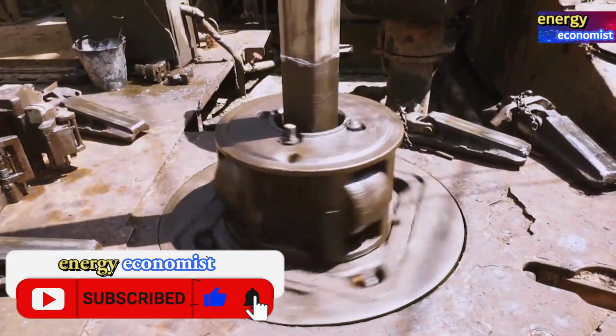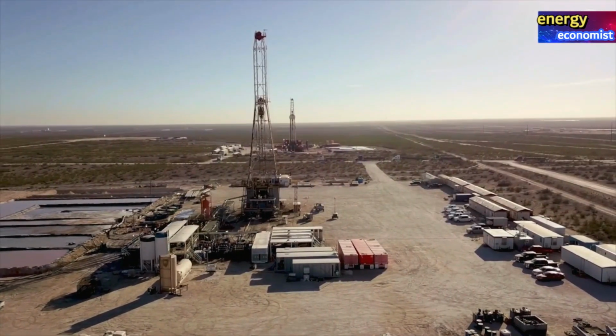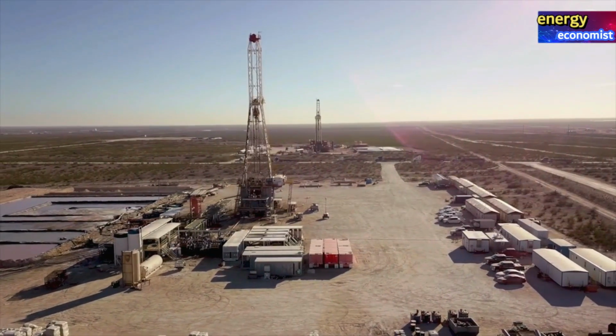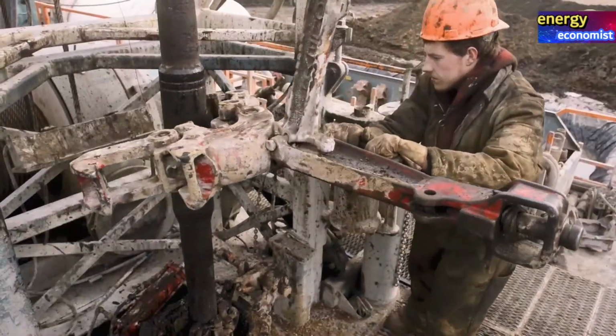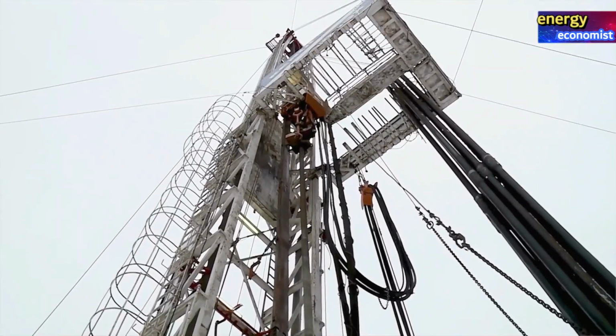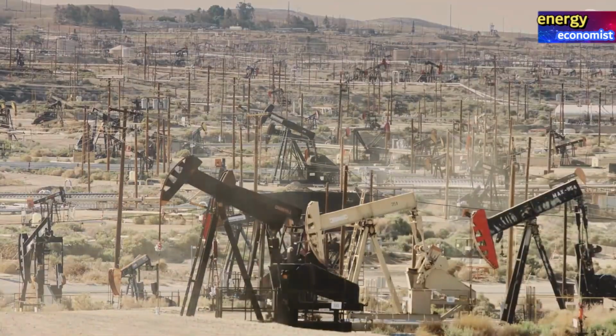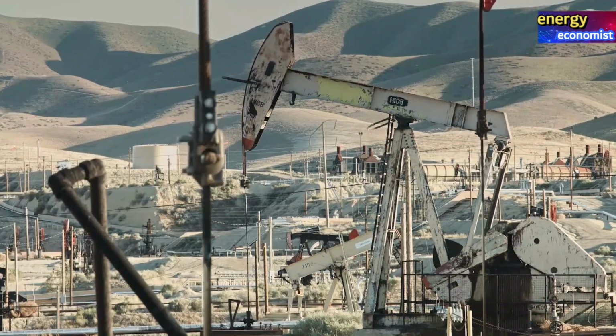For both volatile oil and black oil, the initial reservoir temperature is below the critical point, and the fluid is therefore a liquid in the reservoir. As the pressure drops, the bubble point is eventually reached, and the first bubble of gas is released from the liquid. The composition of this gas will be made up of the more volatile components of the mixture.